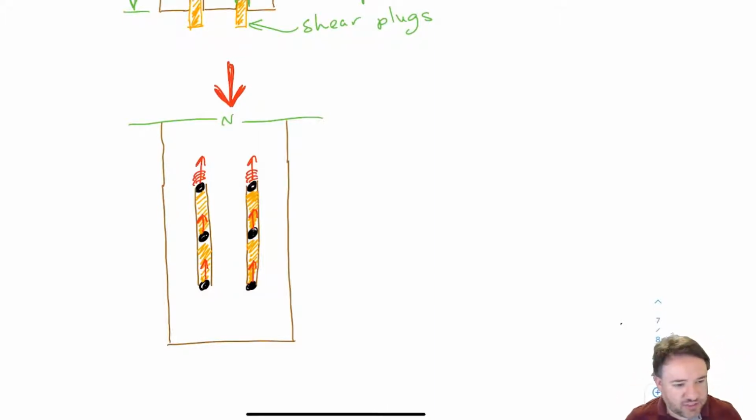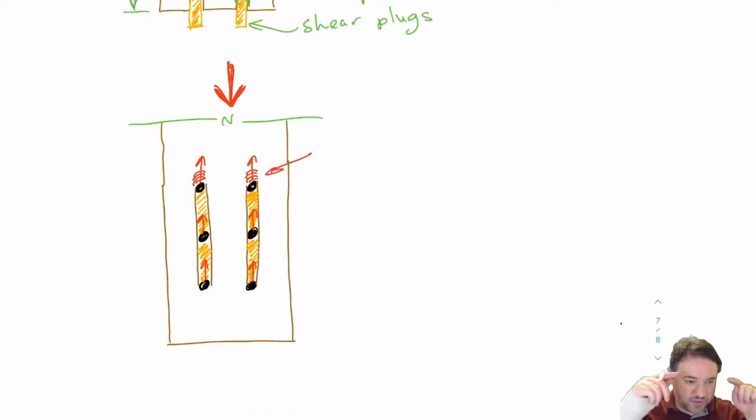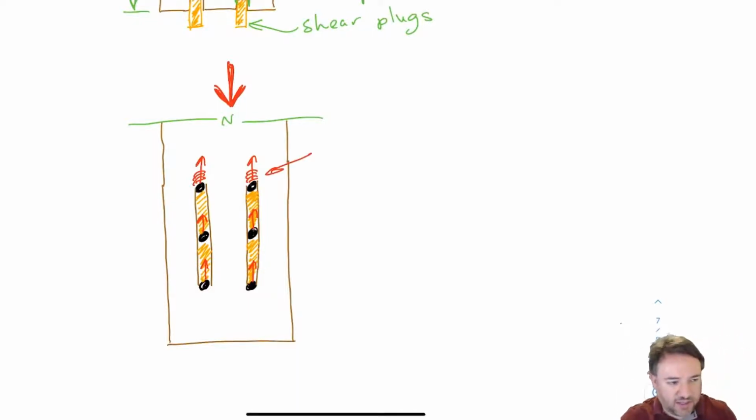Now, where are the plugs going to go? Well, obviously we're going to have some embedment failure of the top bolts so that the bolts will move up over here, right? So the bolts are moving up because of an embedment failure. And then the rest of the wood is failing as plugs, those orange plugs of wood, which are just chunks of wood being pushed up. And we calculate basically the exact same way.